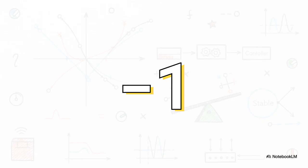Moving on, we need our asymptotes, those guidelines pointing off to infinity. To find the center point of those guidelines, we just take the average of our poles. 0 minus 1 minus 2 equals -3. Divide that by our 3 branches, and you get -1. It's really that simple. -1 is our exact centroid. It's the anchor for our whole drawing.